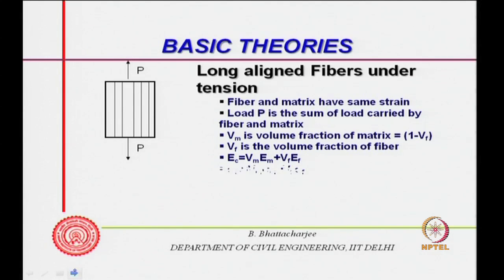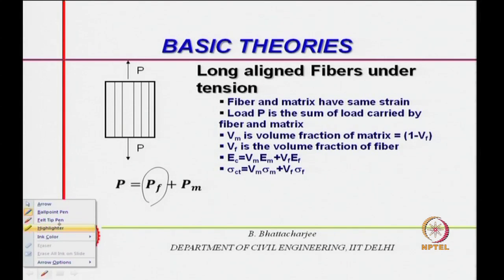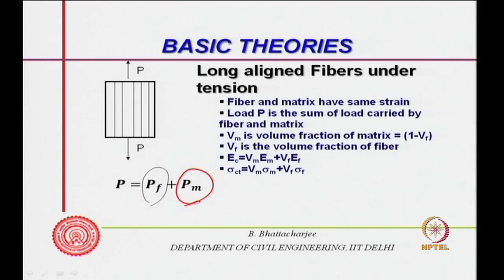Now, since we will look into this, last class also we mentioned, total force is P equals P f plus P m, the load carried by the fiber and the load carried by the matrix. The force P is the load applied. So, matrix carries P m. Therefore, this is nothing but sigma, the stress in the composite, into the area of the composite, which is the sum total.